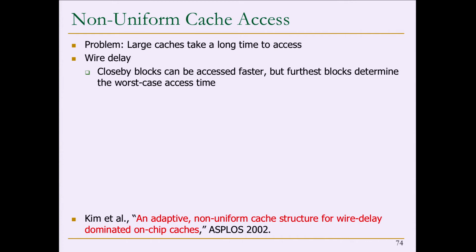If you remember the tiered latency DRAM idea, we tried to segment that bit line such that some part of your DRAM was faster, some other part was slower, right? The part that's closer to the sense amplifiers, that is segmented out when you isolate that part, is much faster, right? It's a very similar idea. Make the caches non-uniform access. Tiered latency DRAM makes the DRAM chip non-uniform access. The idea is to have variable access latency in a single cache. So how do you do it?